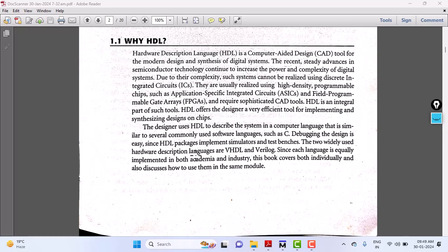If you ask me, can I call 74 series ICs like 7486 or 7404 application specific? You can't call them that, because they are all general purpose ICs, which everybody will use. They are not meant for specific applications. You can customize them for any application, so they are general purpose ICs. Application specific ICs are totally different. I hope you understood the meaning of application specific integrated circuits.